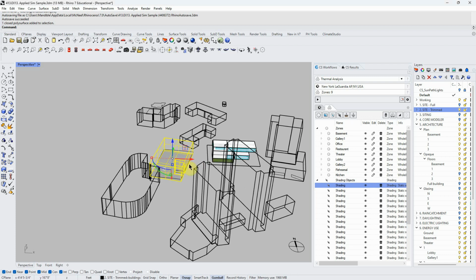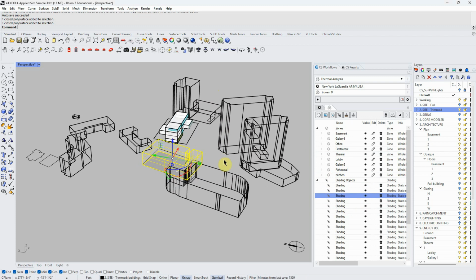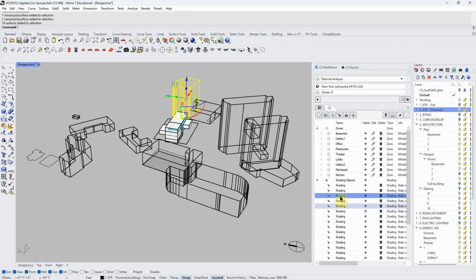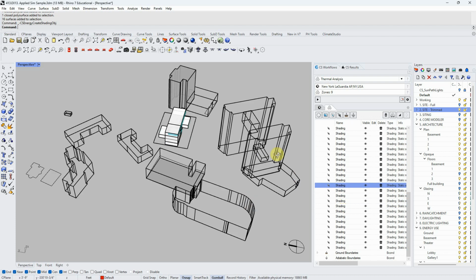It's interesting. Maybe it was grouped. The point is that what it just did needs to happen. It needs to break up all. If you have a building that's a group or a polysurface, you need to explode it. Let me see if it works with this one. Yeah, I can't remember if I exploded these myself or if the model does, but I think you have to do it yourself. Anyway, the point is if you want the context to work, they need to be single surfaces.